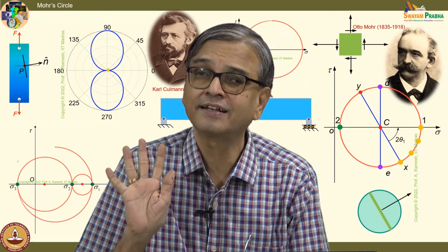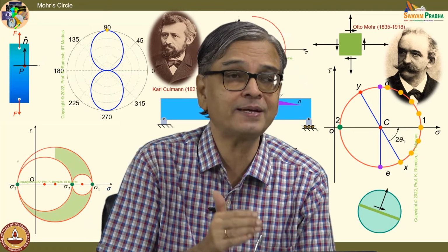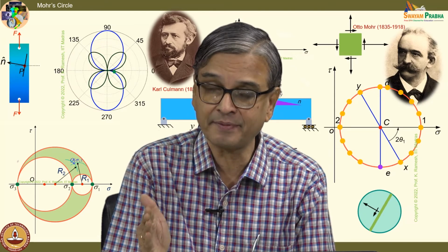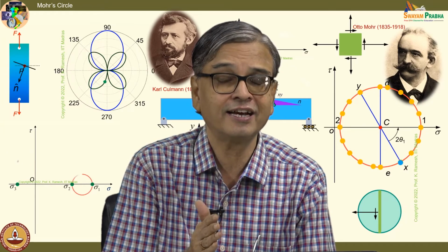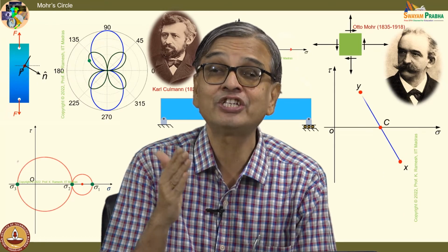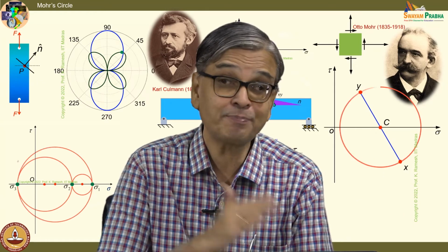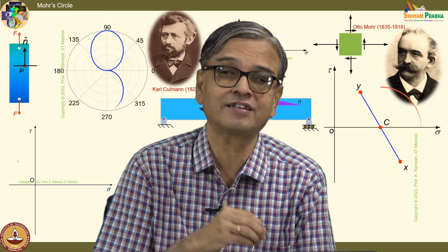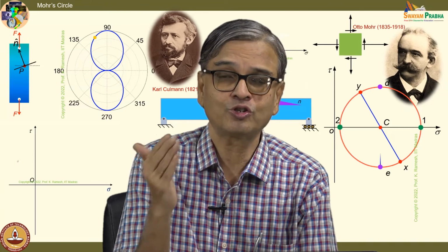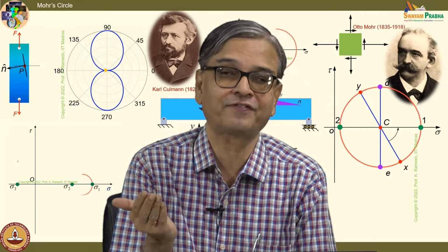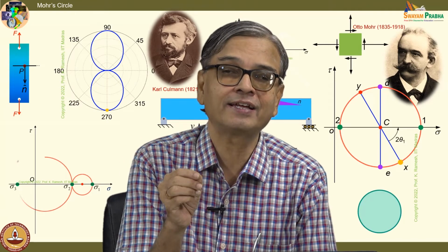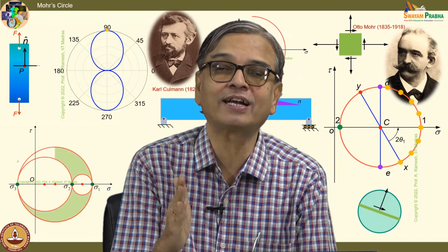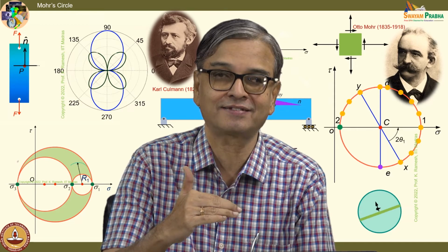Is the idea clear? In one case, it is dictated by the plane on which the normal stress exceeds the limit. In another case, it is on a plane where shear exceeds the limit. These planes are different. See, one of the difficult concepts in stress is, we are also going to have a detailed discussion on a free surface. When you take a point, what happens on a plane is what you have to look at. You can have infinite number of planes.